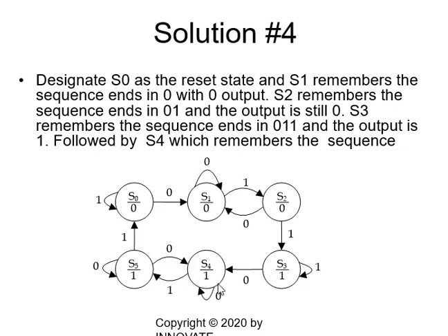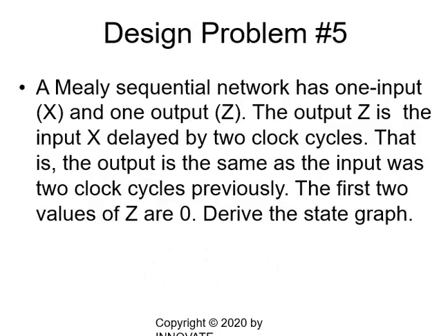Because I will get here 0, 1, 1, then 1, 1, 1, I will remain, and the output will accordingly be 0 until the detection of the complete code, which is 0, 1, 1, takes place and fluctuates back to 1. So the network will be a perfect solution. And that completes design problem number 4. We'll go to the next one, which is design problem number 5.